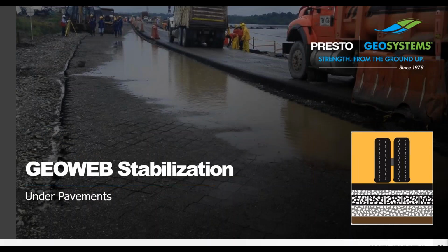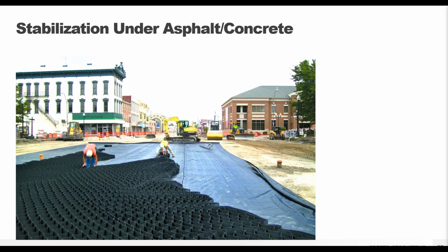And now I want to, again, switch gears, go back to how the GeoWeb system can help, but this time it's going to be underneath pavements. So no longer a gravel surface, but now we're talking asphalt, concrete, any sort of hard surface roadway. So the GeoWeb system can be used both in place of or in conjunction with your traditional aggregate layer that would be placed beneath your asphalt or concrete road surface.